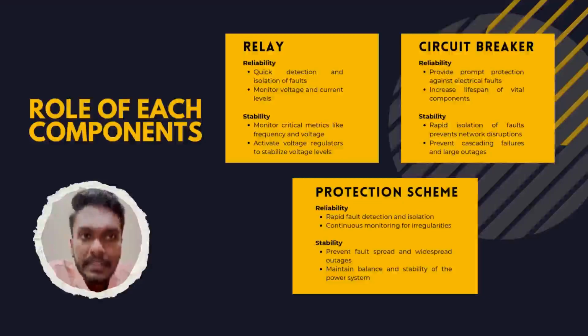When a fault is detected, relays trigger the protection device, like a circuit breaker, to disconnect the malfunctioning section, preventing further disturbance and minimizing the outage duration.